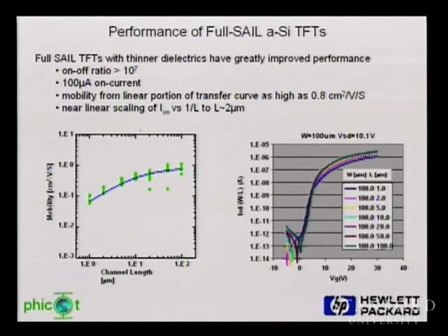So I guess all this is great. It's a good story, but if you can't actually make anything with it, then it's really not that exciting. And so it was a year ago, this last February, that we demonstrated the world's first displays made completely with roll-to-roll processes. Again, this was done in partnership with E-Ink. We were using their electrophoretic medium. This is showing some of the amorphous silicon transistors that we use in these devices.